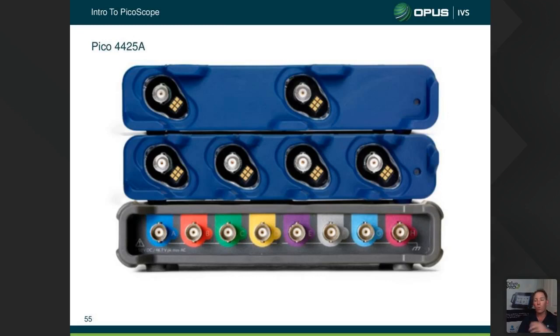So if I do automotive, I go through to my guided test and it tells me to plug this one in. If I plug into the wrong channel, the Pico will automatically swap channels and do the value on channel B rather than channel A if I don't have it plugged in right. It is pretty good. It's about the only hardware difference between the two, where it just picks up whatever we've got plugged into it. So it could be a bit of a time saver.